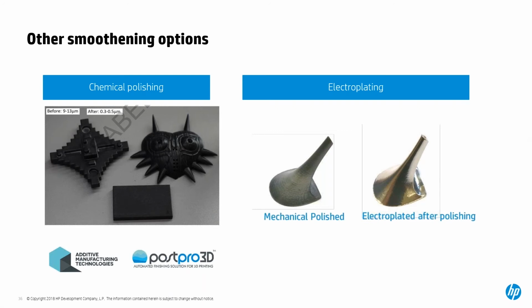Here, one important thing is that, for example, in the FDM parts, acetone could be used in order to polish them because the ABS is easily attacked by different chemicals. But the nylons are very resistant to several chemicals, and actually this is an advantage in most cases, because that means that we can work with different fluids without having a chemical attack.